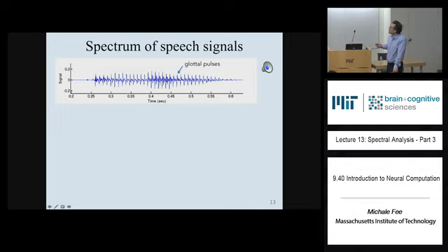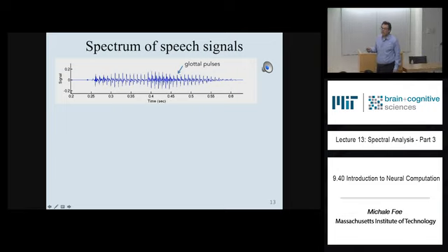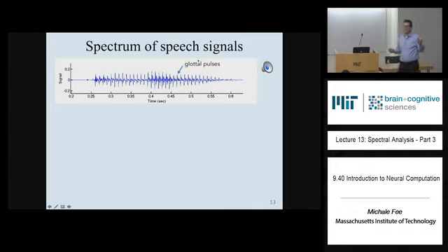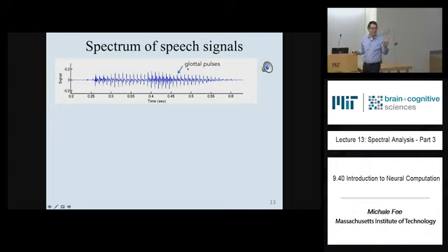Okay, but you can see there's a lot of other structure that changes in this signal through time. But let's start by just looking at the spectrum of that whole signal. Now, what might we expect? If you have periodic pulses at 10 millisecond period, what should the spectrum look like? If you have a train of pulses, let's say delta functions with 10 millisecond period, what would the spectrum of that look like? Most, yes, there would be, but there would be other things as well.